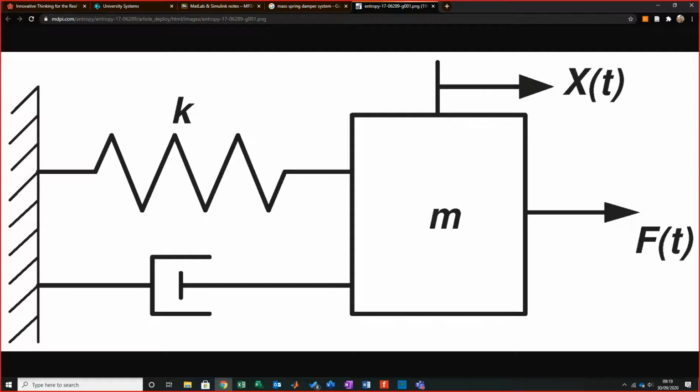What we need to choose is where our starting geometric representation in space is. Where are we going to start this simulation from? The obvious thing that we know is that that fixture is not going to move, so this is a great place to start. So we need a fixed point. We need a 0, 0, 0. For those of you who are CAD savvy, we need a datum. We need a starting position.